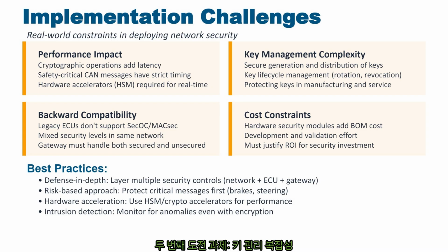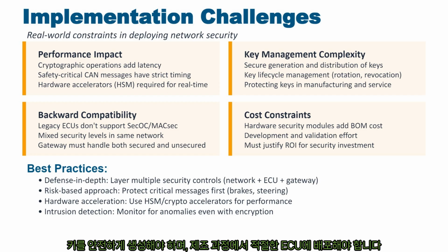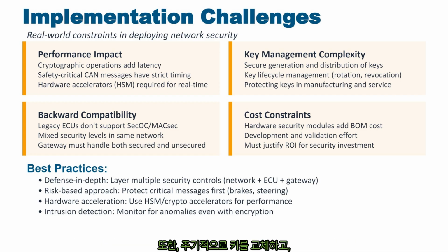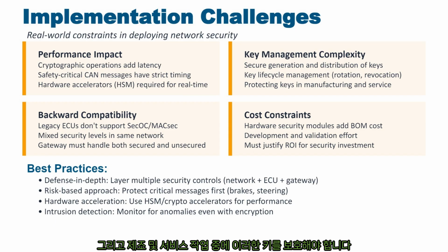Second challenge, key management complexity. You need to securely generate keys. You need to distribute them to the right ECUs during manufacturing. You need lifecycle management, rotating keys periodically, revoking compromised keys. And you need to protect those keys during manufacturing and service operations. This is one of the hardest problems in automotive security.